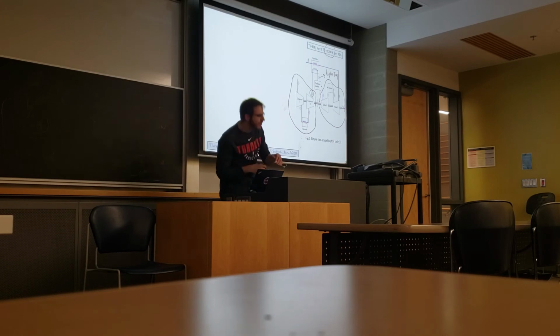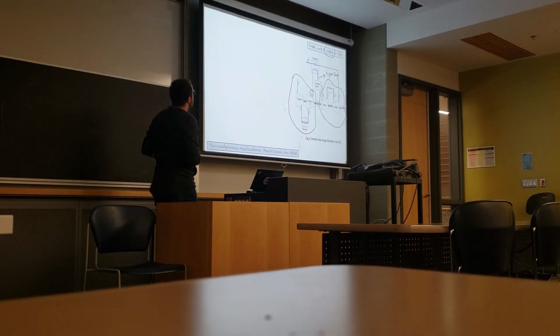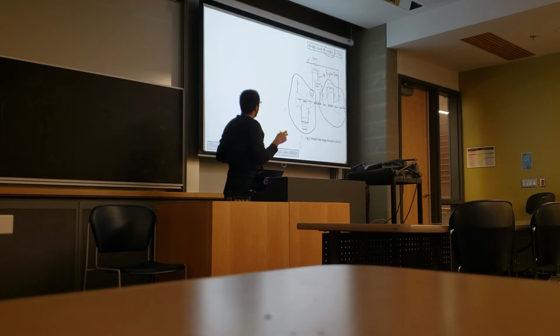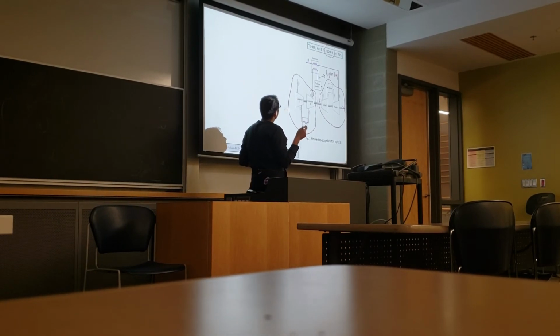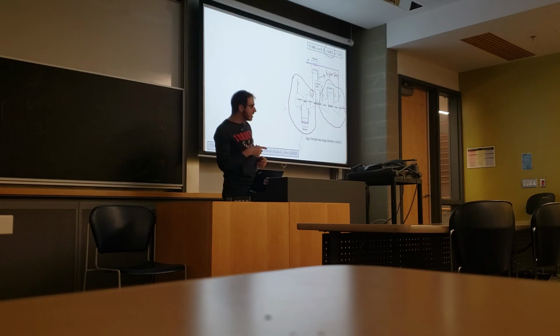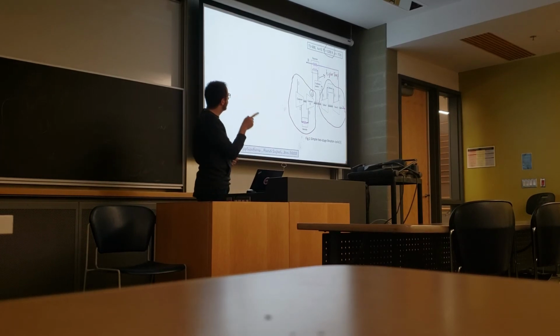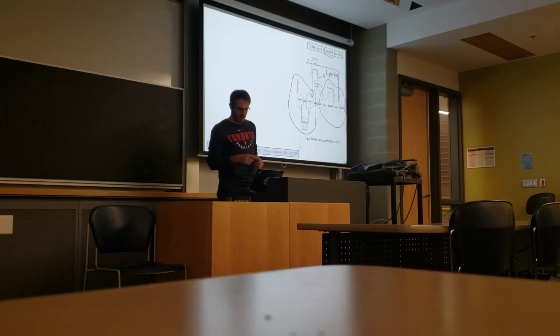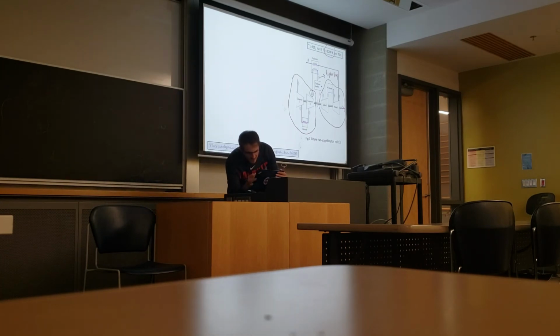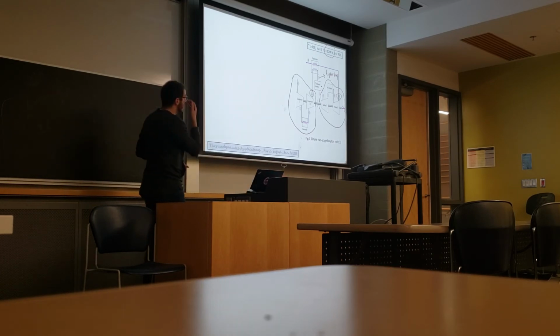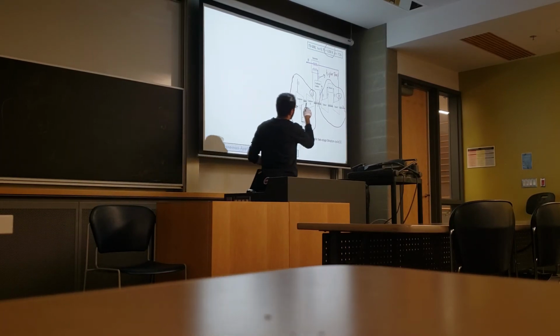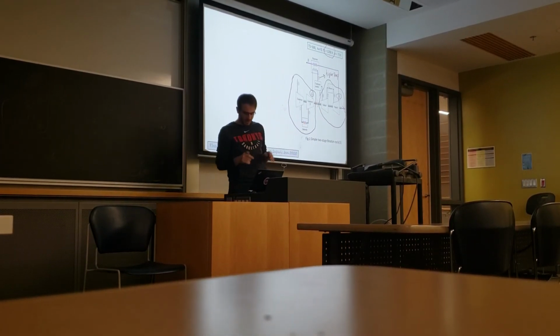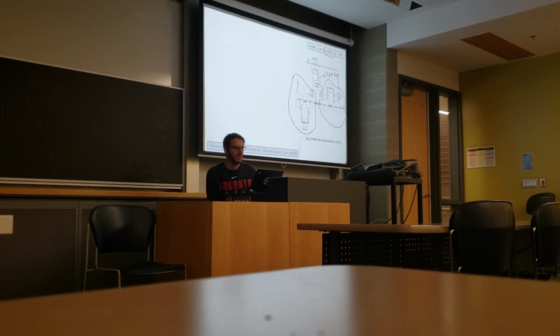So this heat recovery is beneficial in economic aspects and also energetic aspect because you consume less fuel and also you increase your efficiency, which will be shown. So basically here 5 is at a higher temperature. So how do we increase this temperature? From the exhaust gases that go out of the second stage of the turbine in 9. So based on design of the system and the temperature of 9, we can do this, not every time. But in this case, let's see.